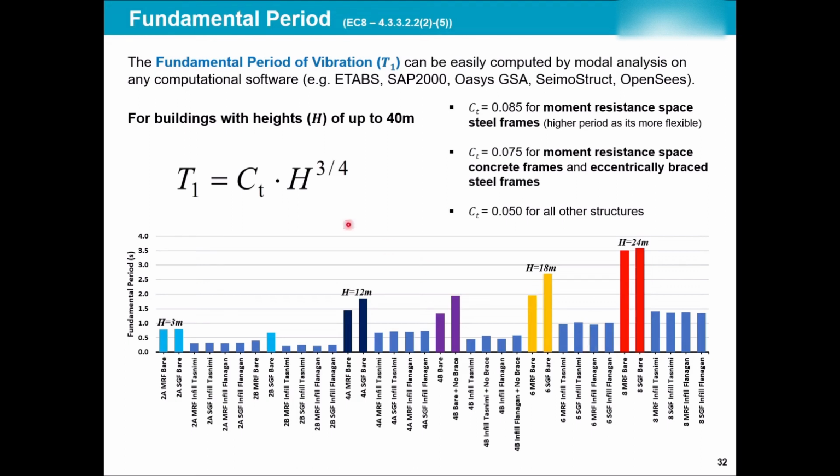This is just an indicative formulation, again based on many years of study, but when you have the opportunity to figure out what is the actual fundamental period of your structure, conducting a modal analysis of your building, which you already know how to do and you will practice more and more, it's better to use that instead of this formulation that the Eurocode suggests.